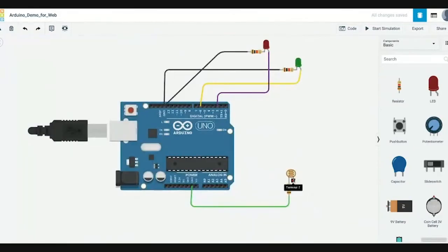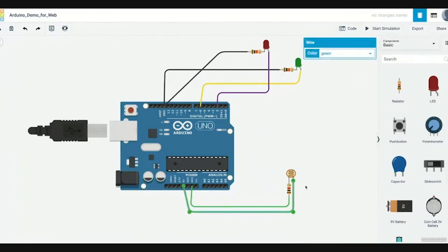We're now going to have to connect the photoresistor leg on the side that hasn't been connected to a power supply, and in this case we can use 3.3 volts, but let's use 5 for this example. We've now closed our circuit and this photocell is receiving an electrical signal, but let's remember to change the colors of our wires so that we can easily tell that there is a signal of power or 5 volts coming in on a red wire, and change all of your ground wires to be black.